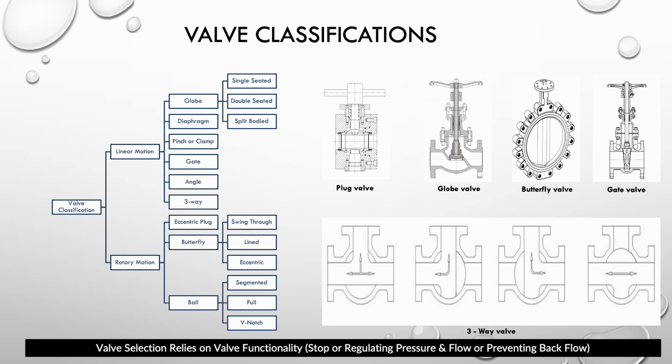Gate valves, on the other hand, are mostly used in a process as a shut-off valve, like an XV. They're going to be either on or off. The perfect thing about them is they have minimum pressure drop. Whenever they are open 100%, you want that valve to be almost non-existent in terms of pressure drop. You don't want to waste so much energy around them because they are literally 100% open or almost completely closed. You want them to be doing their job without wasting so much energy. That's basically the role of a gate valve.